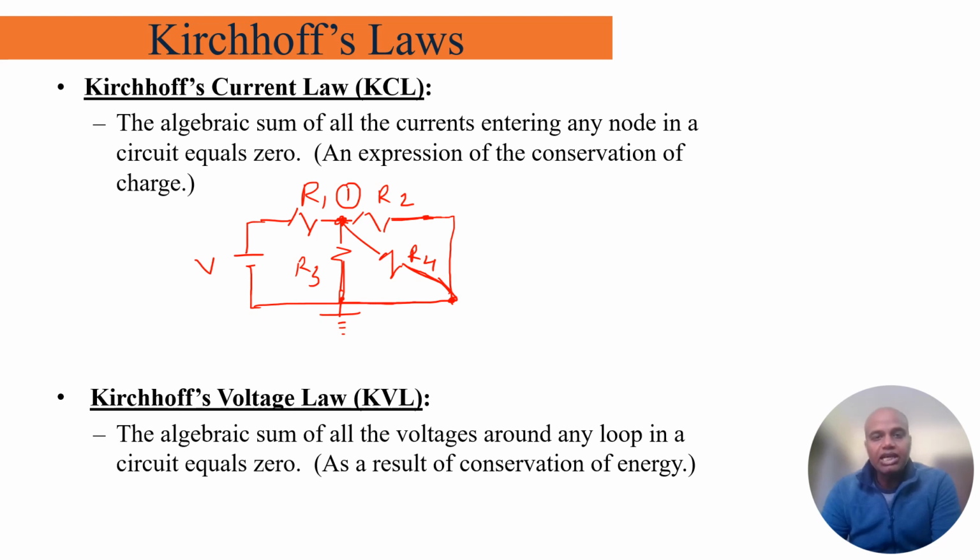Here we need to understand that all these second terminals, whether of R2, R4 or R3, are meeting at this point. So the potential of these points, the second terminal of R2, the second terminal of R4, and similarly the second terminal of R3, are all at the same potential, which we have considered as the reference point or ground level.